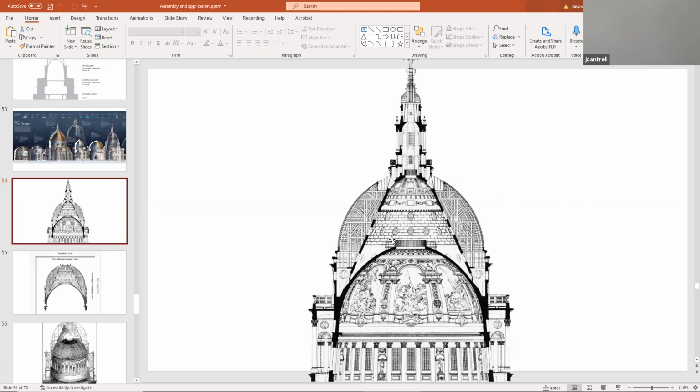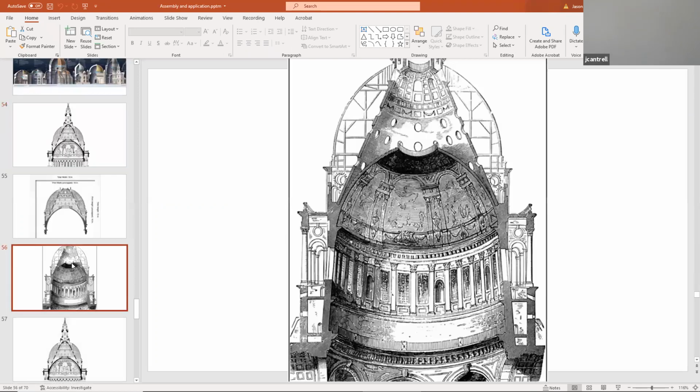So by having the scale of the interior dome proportioned for the scale of the actual church, there are different relationships here. The outer dome is scaled for the outside, for the city of London. And the structure, which is not visible, is proportioned for the cupola that transfers the load from the top down to the sanctuary.